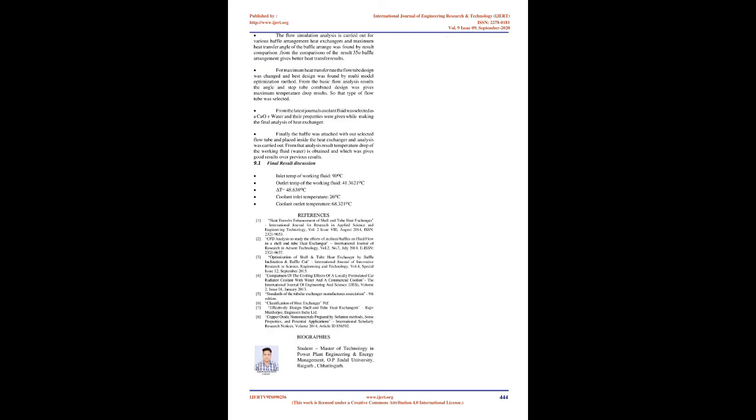The flow simulation analysis is carried out for various baffle arrangement heat exchangers, and the maximum heat transfer angle of the baffle arrangement was found by result comparison. From the comparison of the results, the 35° baffle arrangement gives better heat transfer results. For maximum heat transfer rate the flow tube design was changed, and the best design was found by the multi-model optimization method. From the basic flow analysis results, the angle and step tube combined design gives maximum temperature drop results. So that type of flow tube was selected.